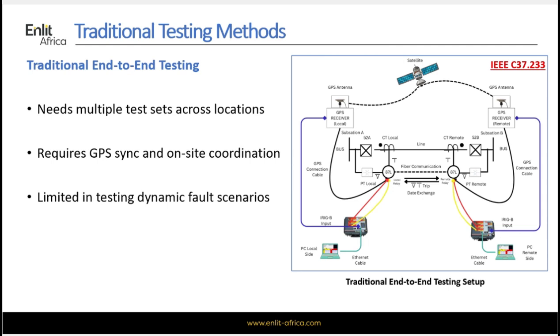This end-to-end testing, which this image shows, is based on the IEEE C37.233 standard. This standard outlines best practices for synchrophasor and time-synchronized testing. While it provides structure, it does not solve the burden of logistics. Cloud-based testing aligns with IEEE C37.233, but improves it practically.